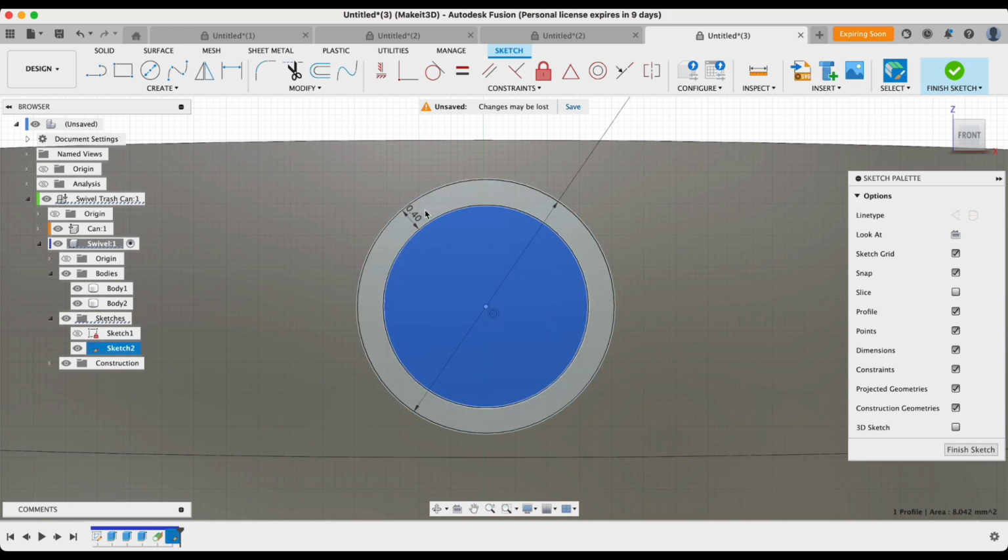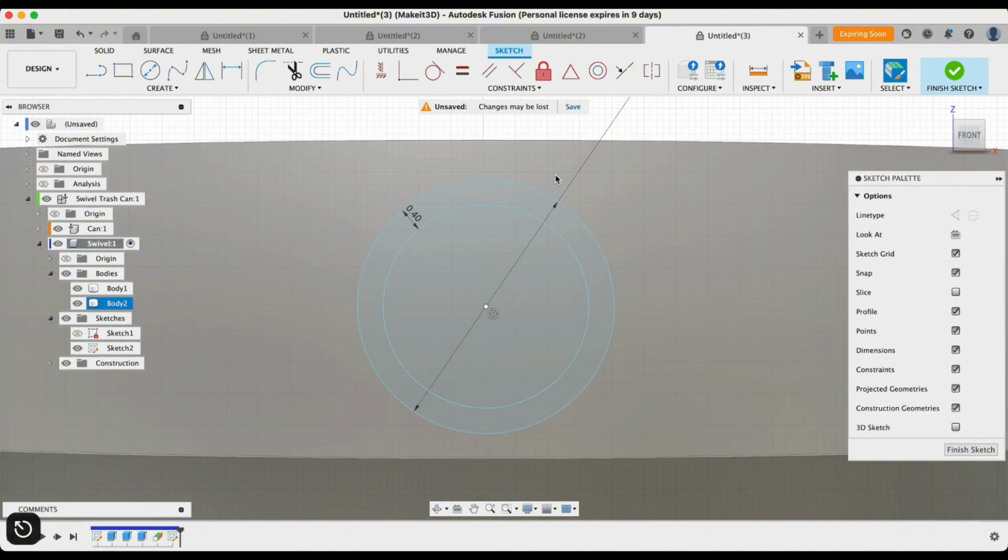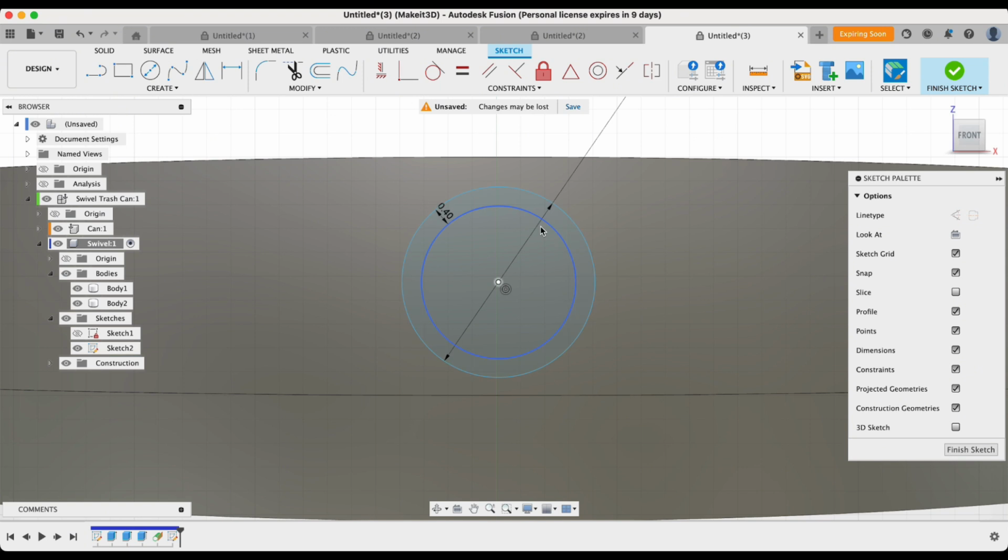This 0.4 is basically just one layer height. So one layer essentially in your slicer, 1 or 2 layers. So this gives it plenty of room for it to actually swivel around in place and actually lock in with your design. Now with that completed, let's go ahead and set up some dimensions, pressing D on our keyboard,